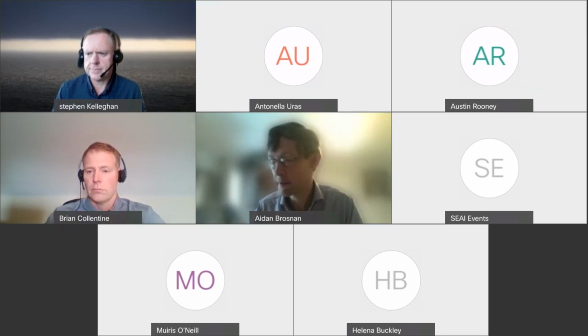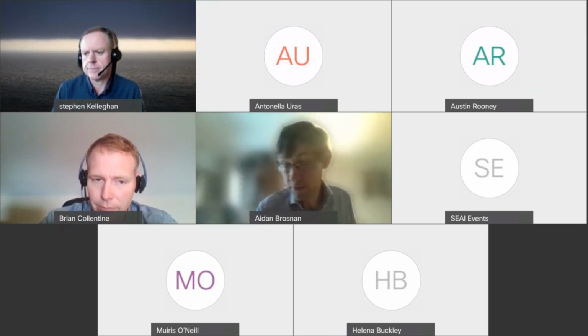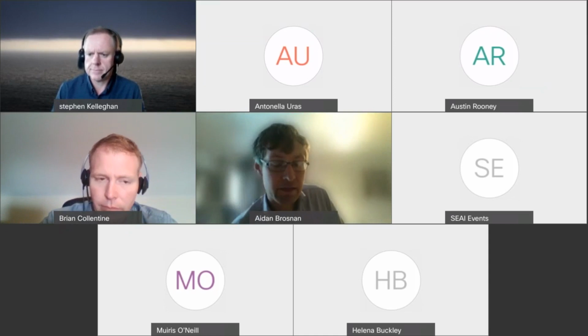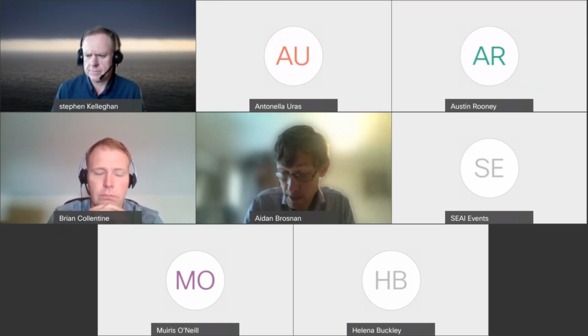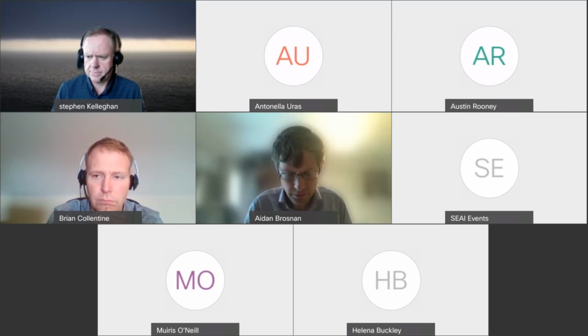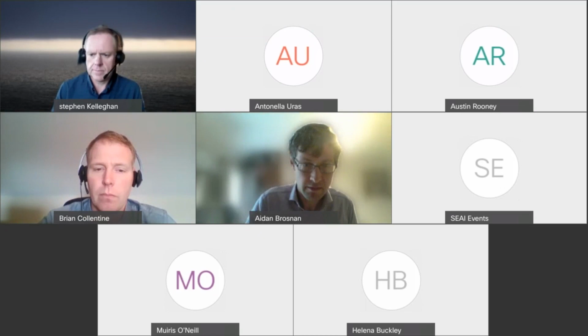I've experimented with it just to try it out. It's useful actually. I say this to assessors. It can be useful just to get a one zone model. In SBEM, if you go rooting around in where your SBEM files are, there's a folder in there with a couple of pre-made SBEM files, and one of them is one zone. It can be handy to save that somewhere and have a one zone model to play around with and try stuff out, because it runs fierce quickly. You can just change something in one zone and see what difference it makes. That's my tip for the day.